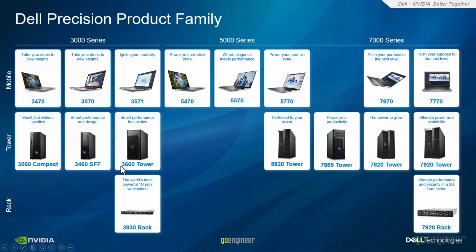But all that being said, like a 3660, you can still put up to an NVIDIA A6000 GPU in that machine, and it will work quite well for Visualize or SOLIDWORKS in general. It just won't allow you to put multiple big NVIDIA GPUs in there. So that's probably fine for most people, but if you want that extended power, you'd look over in this area, okay?